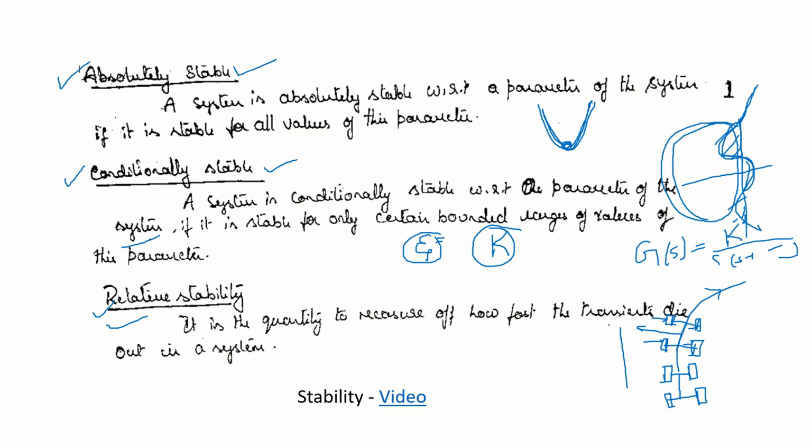The centrifugal force will be trying to pull the car this way, but these lateral forces will keep trying to push the tire like this, so that the car can stay on the path. But what is important here is road friction, the friction between the tire and the road. If that value is alright, fine. If all of a sudden that value decreases, probably you will not have sufficient grip forces and the centrifugal force may simply pull the car out like this. So that's how systems become unstable during operation. Correct?